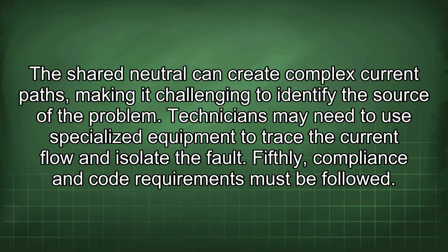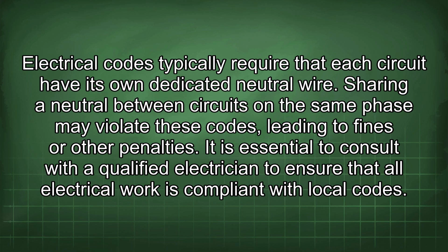Fifthly, compliance and code requirements must be followed. Electrical codes typically require that each circuit have its own dedicated neutral wire. Sharing a neutral between circuits in the same phase may violate these codes, leading to fines or other penalties. It is essential to consult with a qualified electrician to ensure that all electrical work is compliant with local codes.